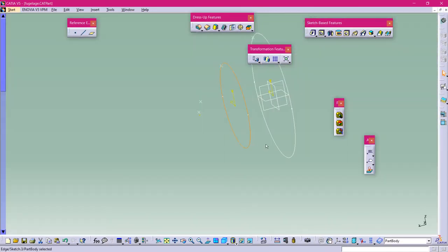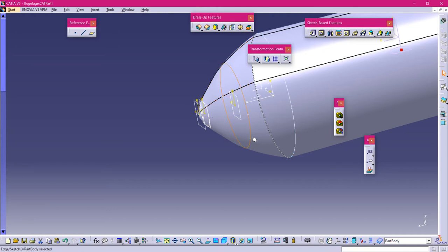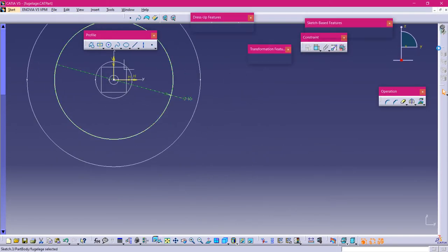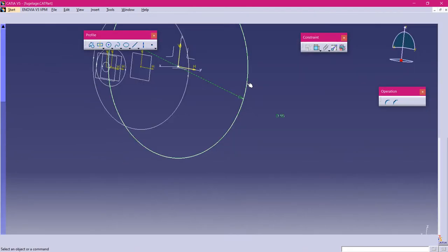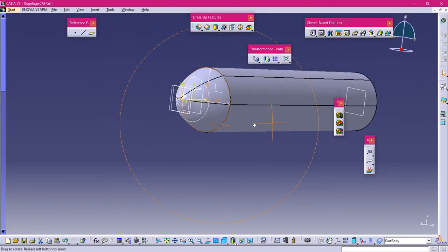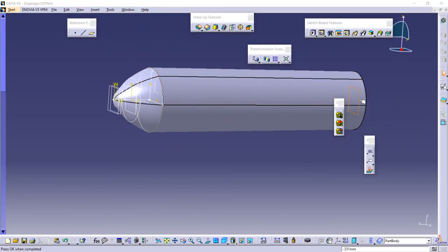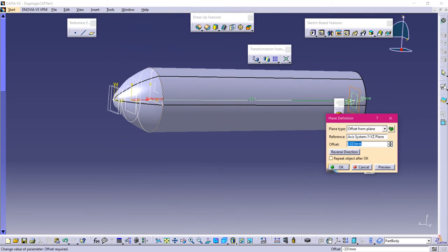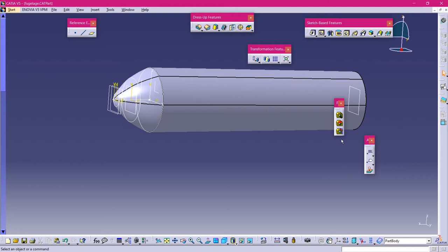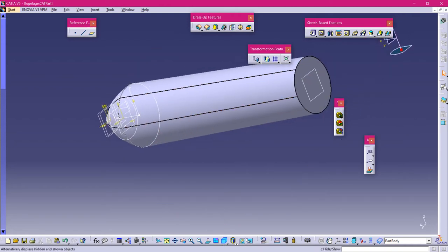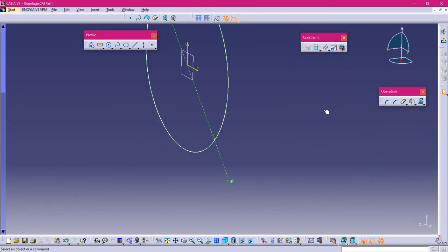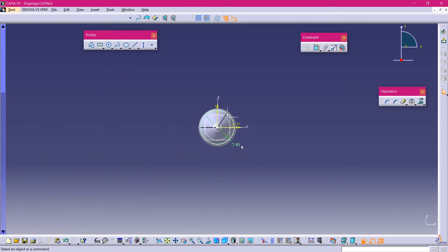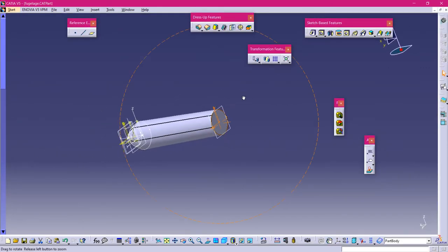Let's just unhide these two even. This was 65 mm diameter, and this is our sketch plane normal, which plane, it's YZ plane, and this is 95 mm diameter. And to the other side of our plane I have selected one more plane, that's minus 331 mm at a distance. So in that I had again drawn a circle, and that's of 85 mm diameter. So all these I have done multi-section,